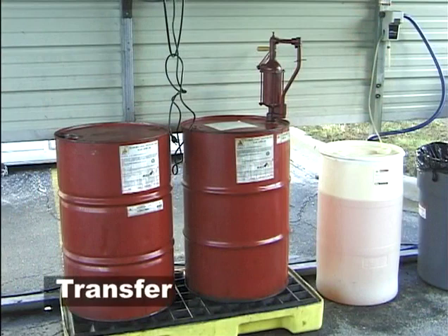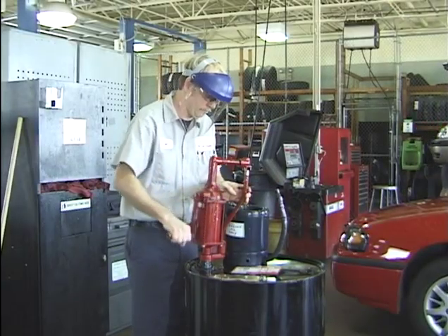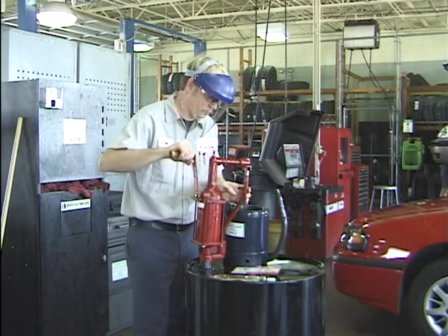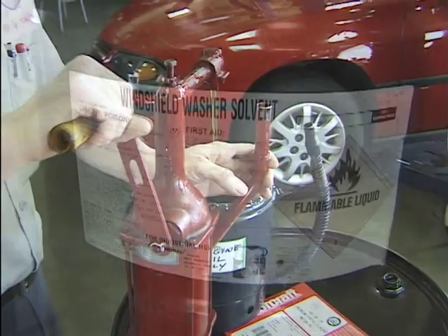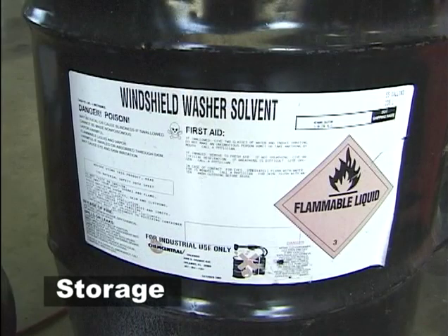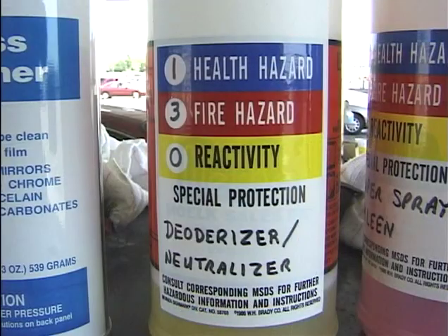Transfer of flammable liquids refers to their removal from storage to the places where they will be used. Liquids can be dispensed from drums by two methods: gravity flow for drums stored horizontally and pump method for drums stored vertically. The typical workplace stores flammable liquids in two ways: reserve storage in drums and storage in small quantities